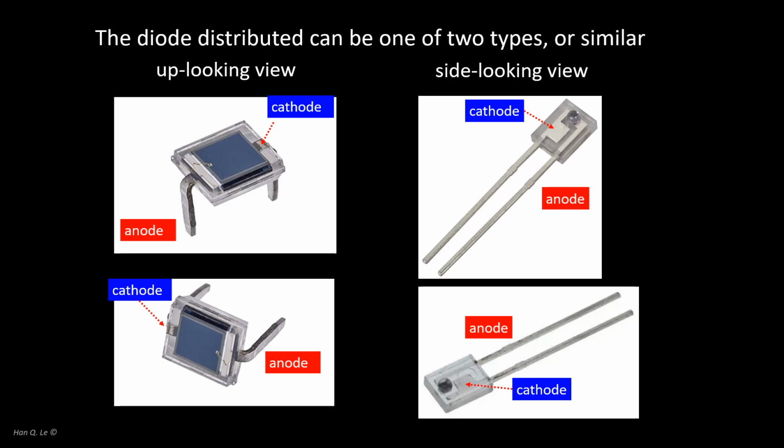Care should be taken with the type that has a bare sensor area, with a thin wire bonded between the anode and the top p-type semiconductor layer. If this wire is broken, the photodiode cannot be used.